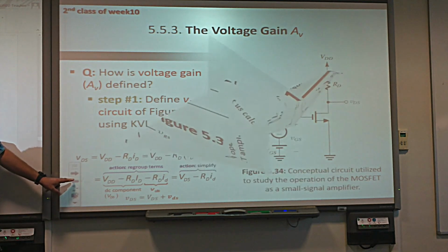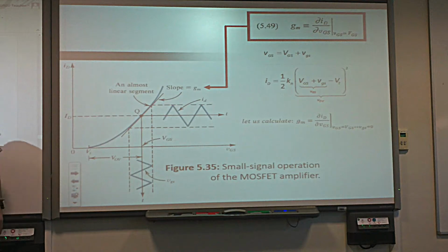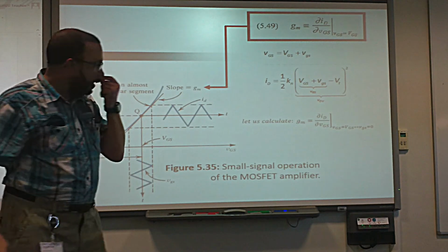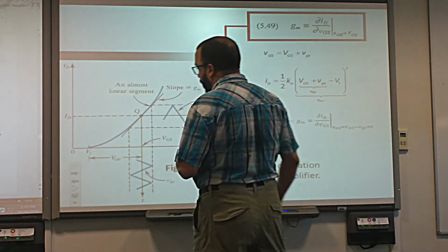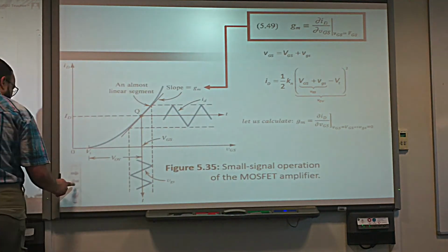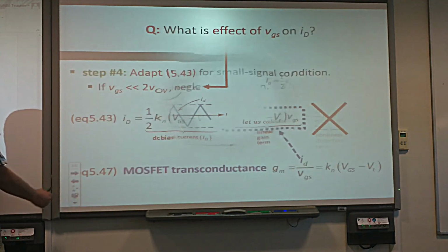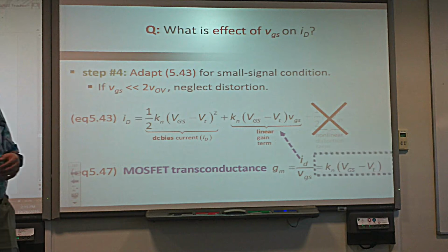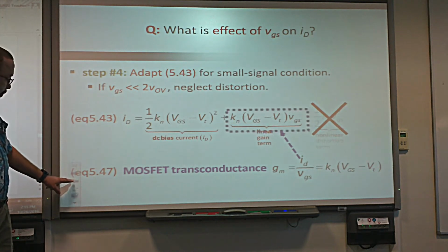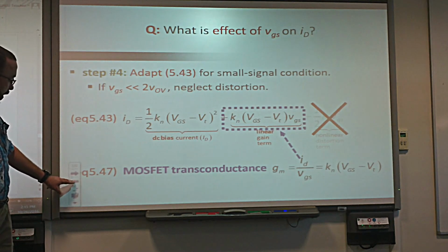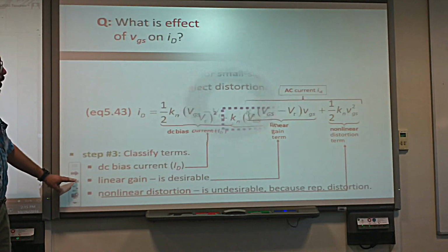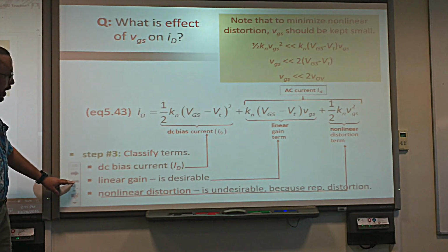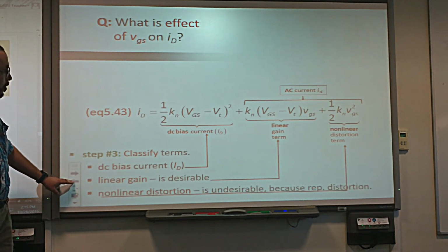We have spoken about the trans-conductance, and we said that we call it trans-conductance because the MOSFET, when used as an amplifier, in which region does it have to be? Saturation. Exactly, because the MOSFET in saturation works like a VCCS, voltage controlled current source.